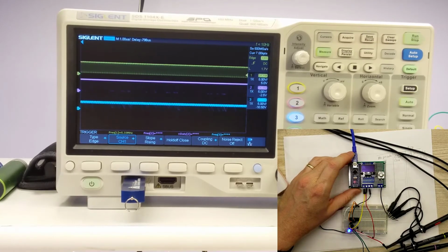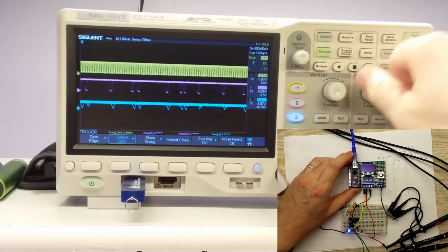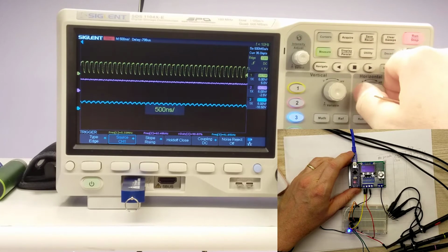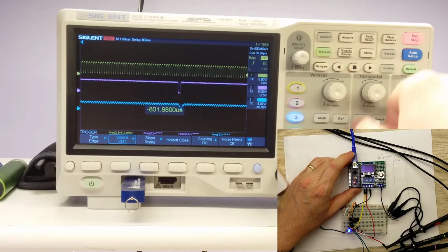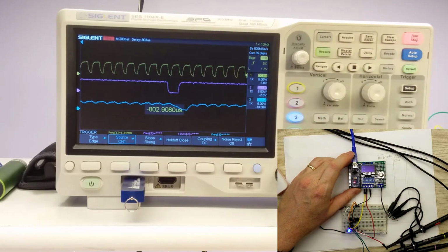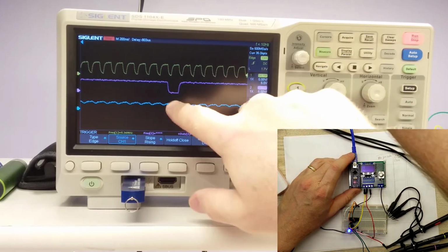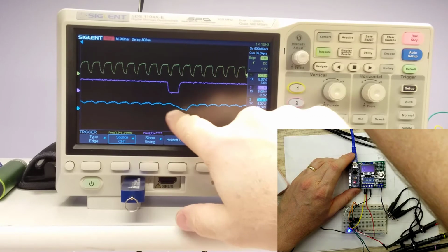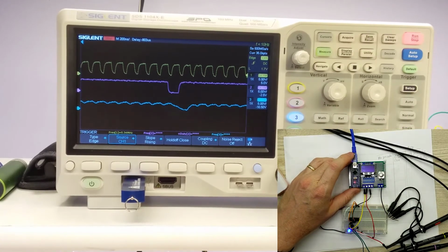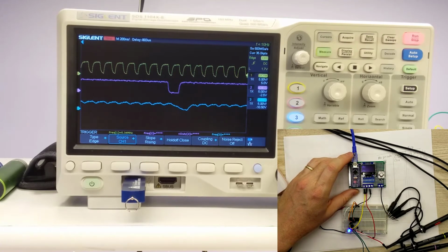Now we've got that up at 5.3 megahertz, and I'll just go ahead and stop that so we can take a look at what it's doing. Let's zoom out a little bit first. And it kind of looks like it did before with some of the other ones up at this frequency. Yeah, it's not really dropping hard there when that signal goes down. You can see it is starting to go down, but it definitely isn't on the bottom. And then it kind of peaked out right there when that other one went ground on channel 1. But kind of interesting. This one definitely didn't hold up as well as the AND gate did, but you know, it did okay.